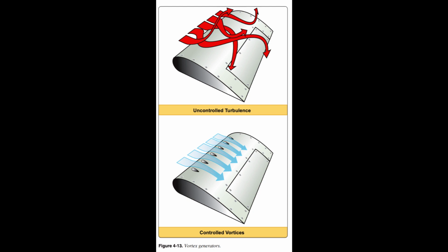Most small airplanes maintain a speed well in excess of 1.3 times VSO on an instrument approach. An airplane with a stall speed of 50 knots, VSO, has a normal approach speed of 65 knots. However, the same airplane may maintain 90 knots, 1.8 VSO, while on the final segment of an instrument approach. The landing gear will most likely be extended at the beginning of the descent to the minimum descent altitude, or upon intercepting the glide slope of the instrument landing system. The pilot may also select an intermediate flap setting for this phase of the approach.